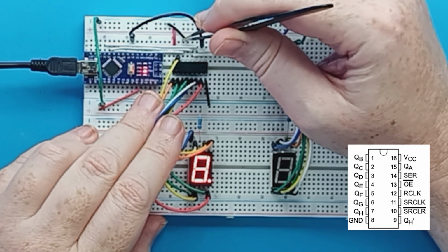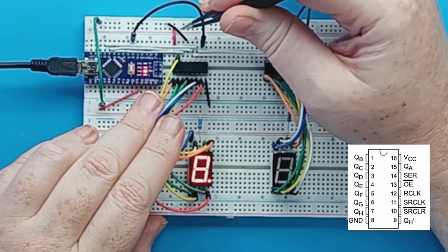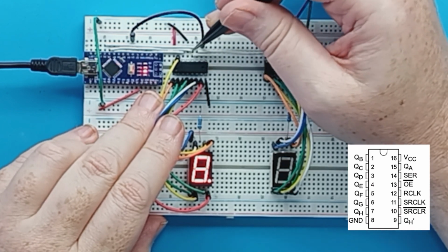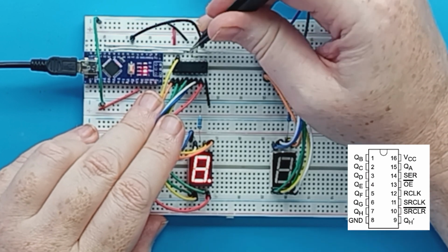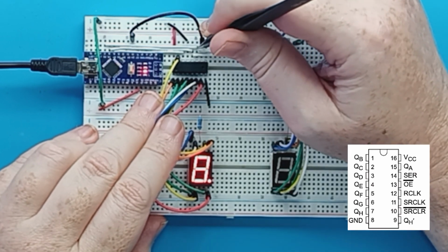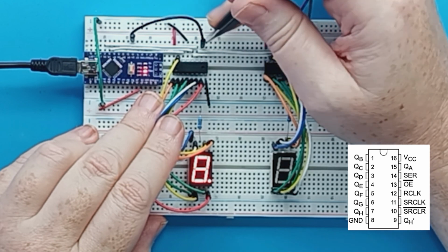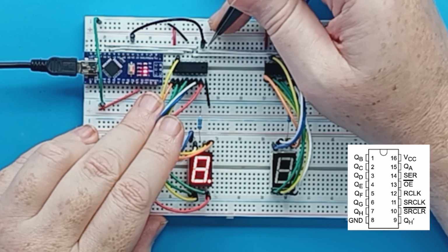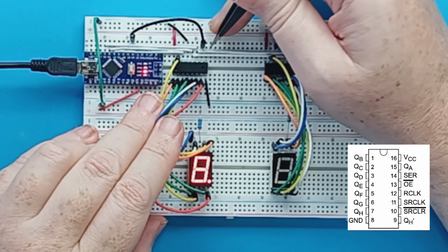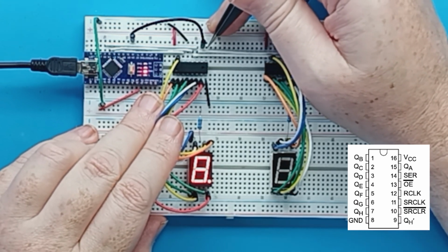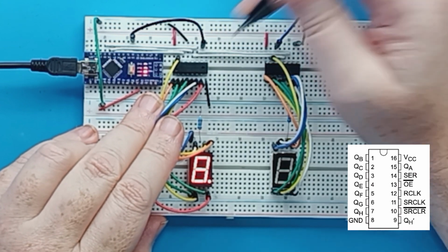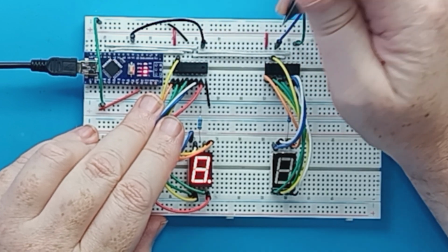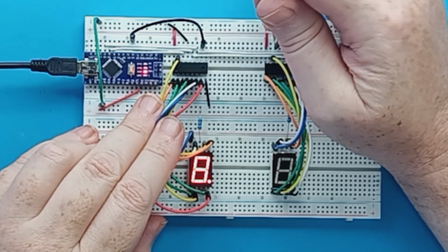Then we have output enable, which we have to pull low in order to enable the output. Then we have the R clock, the latching clock. And then we have the serial data clock, and then we have a reset line, and then there's one final pin, the inverted H, but it's the carry pin. When we want to connect multiple chips together, that's the pin which we're going to be using to connect into the serial input of the next chip.